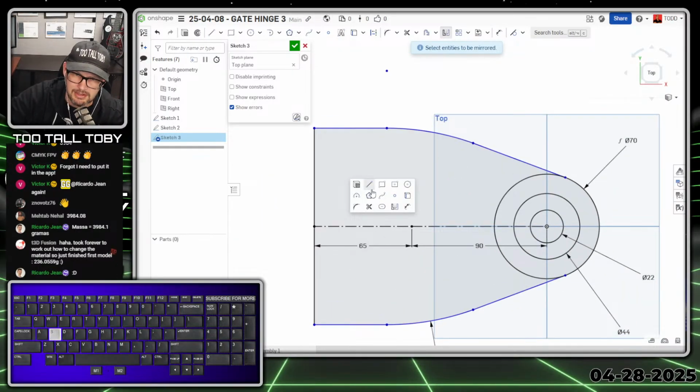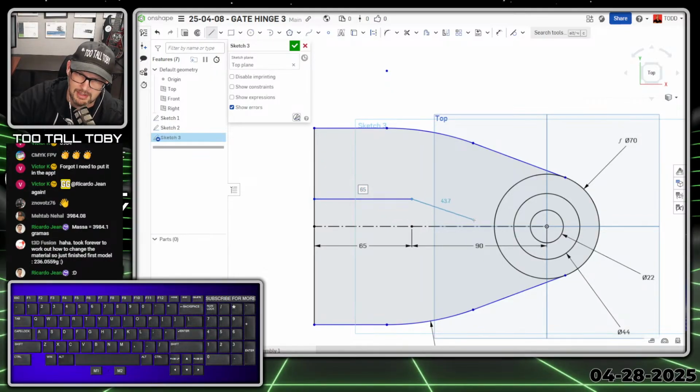So now I'm ready to get in here and create a line. Single click. I could kind of put my mouse over this point so that I get exactly vertical to that point. Single click, move back, move over that end point, and then move around again. Takes me into that little arc command, and then I can close off that geometry. And that's how you can create that tombstone shape all in one pass, and that's a very good workflow to practice.